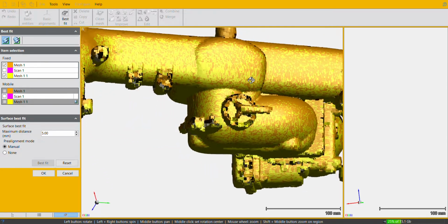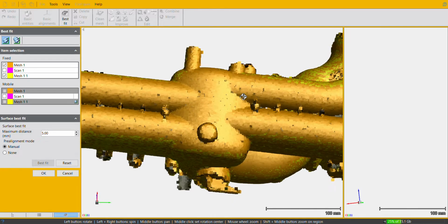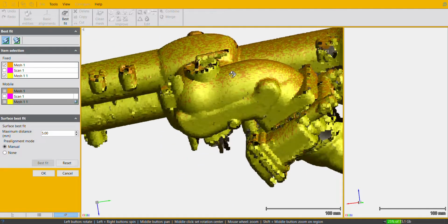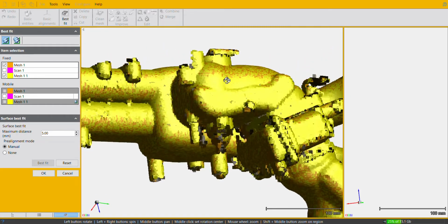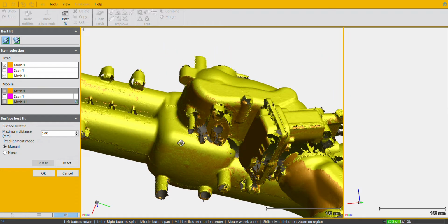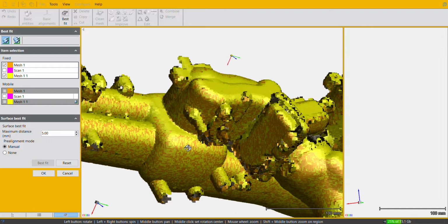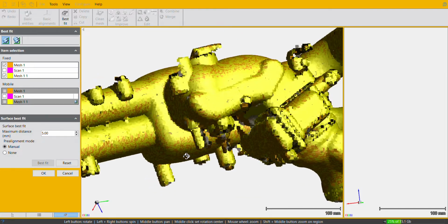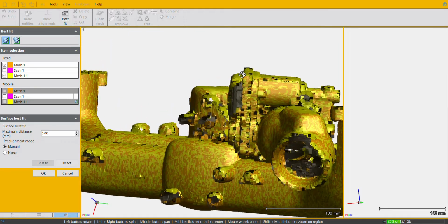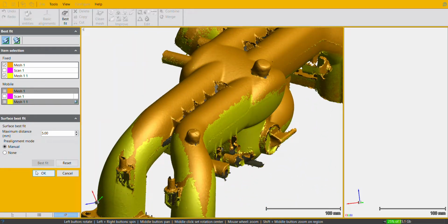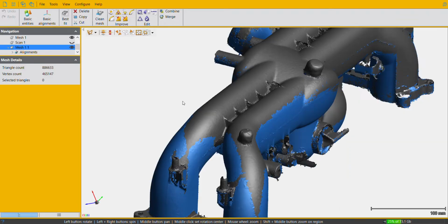And then on round features, since I can't do a top and bottom to make sure the top compares well to the bottom, you can go to round features and see that it rolls over the edge well. When I roll it, it carries over to the other side to where one scan stopped. So it's looking pretty good. I'll go ahead and say it's okay. From this point on, we're going to go ahead and merge.